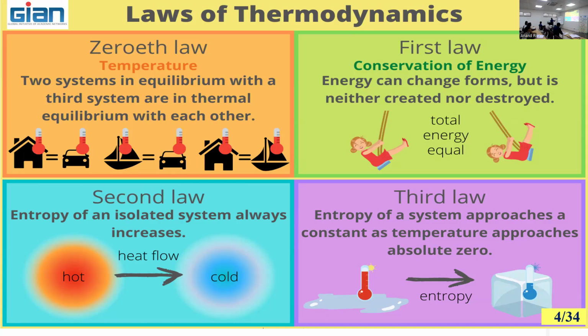So what I mean to say in the second law is that 100% conversion of heat to work is not possible. Some amount of heat has to be rejected. Then the Clausius statement in the second law belongs to refrigeration or heat pump: unless work is provided into the system, you cannot raise the temperature of a particular system to more than the surrounding temperature.